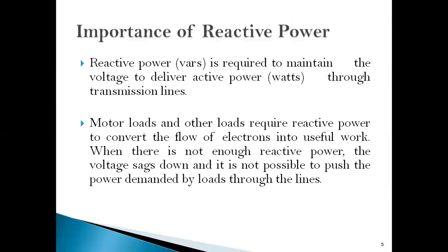Induction motors and other loads require reactive power in order to convert the flow of electrons into useful work. When there is not enough reactive power, voltage sag will be a problem, and it is not possible to push the power demanded by loads through the lines.